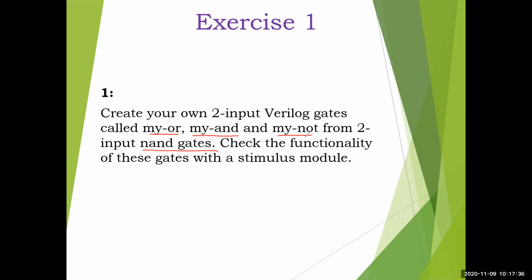First, the NOT gate. I will show you how to construct it from a NAND gate. A NAND gate is a two input gate, but a NOT gate has a single input. I am just recalling this, not explaining much here. For the NOT gate, you just short the inputs.